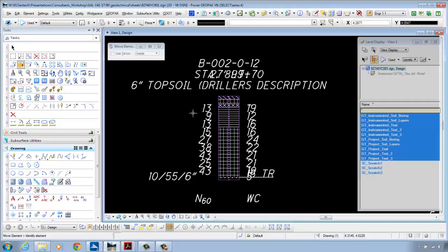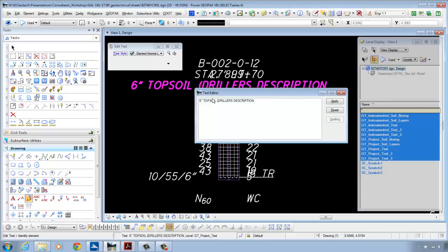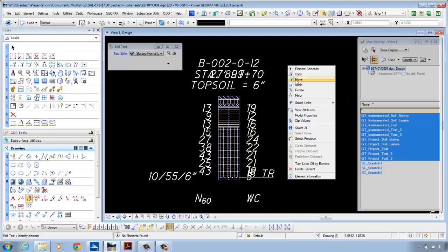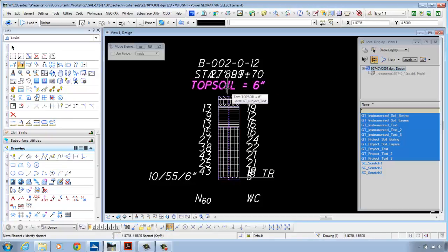If you need to edit a piece of text, make sure that the annotation scale is off, otherwise the text will be the wrong scale once you have a reference file attached to your sheets. If you edit the text in the header block, it will shift off center ever so slightly.